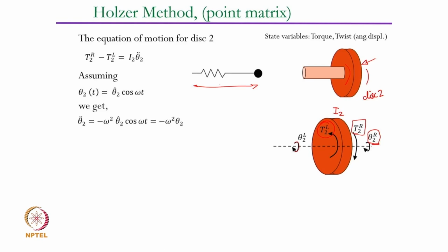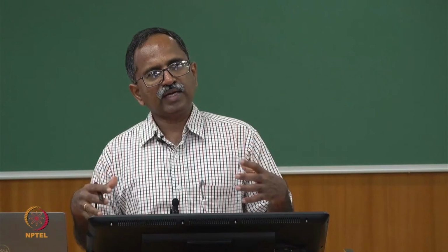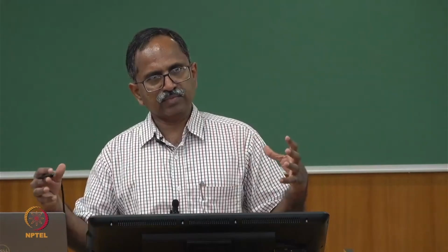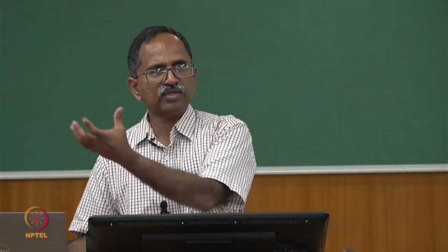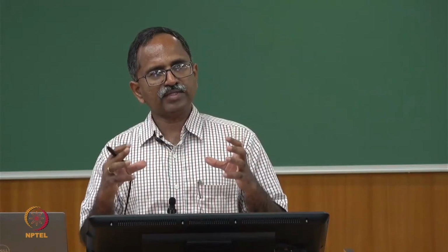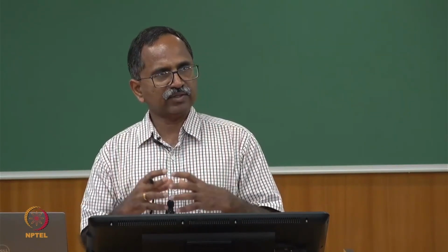At any of the eigenvalues, the entire system, be it segment 1, segment 2, segment 3, segment n, all these segments are going to go through a principal mode or normal mode of vibration, wherein all the elements are going to oscillate at the same natural frequency. It is not going to be like segment 1 vibrates with the first natural frequency, segment n vibrates with the 10th natural frequency. It does not happen like that.